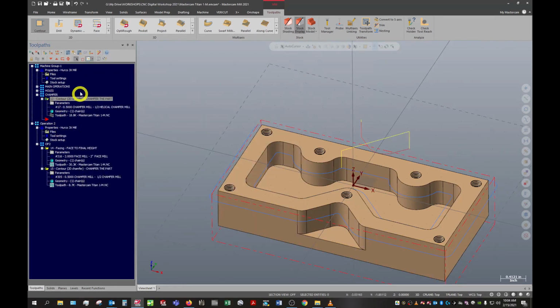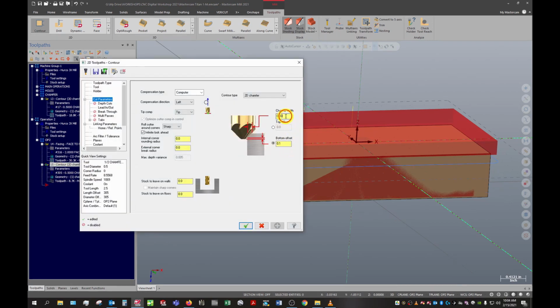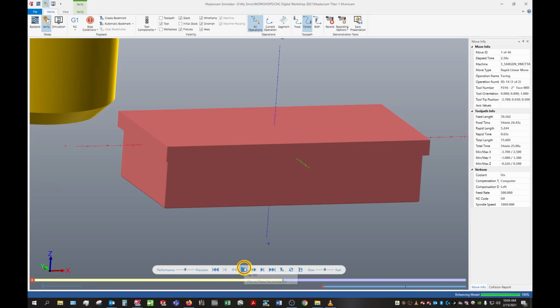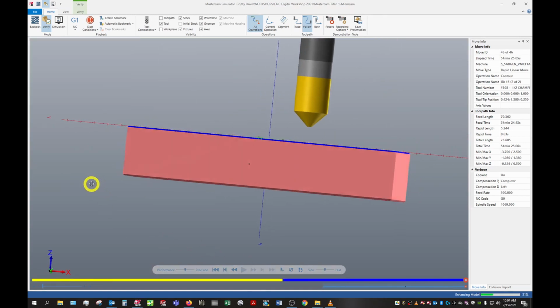And you can see I've gone and moved my little insert arrow back into the first toolpath group. So I want to go ahead and make sure that's down here if I had more toolpaths to work on. So we'll change this to 20 thousandths. Regenerate our dirty toolpath. And again, run through our verify. Right on. So now we've got two matching chamfers.